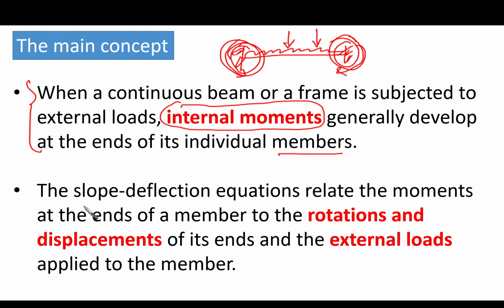The slope deflection equations relate the moments at the ends. Now, to understand the role of the slope deflection equations, it is going to make a relation between the moments that are going to be developed at the ends of the beam and the rotations and displacements of its ends and the external loads.